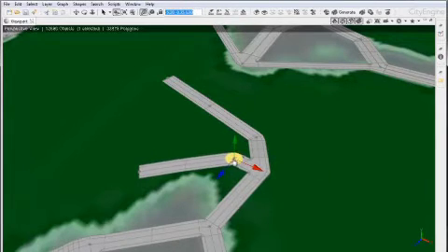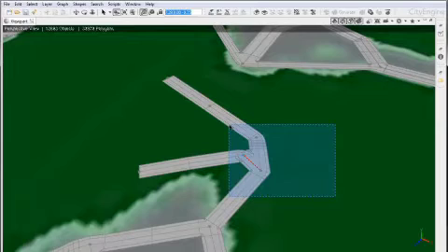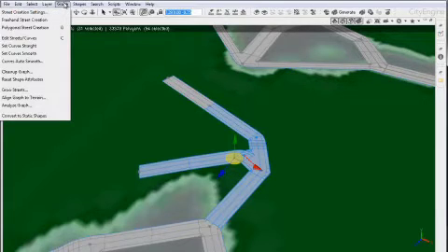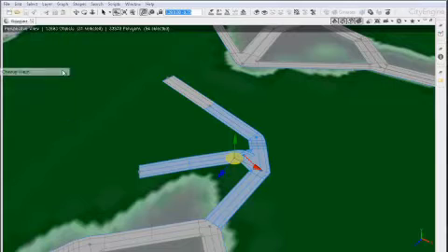But depending on the amount of segments you have in your scene, or the amount of time you want to spend cleaning those data sets, it may also be useful just to use the cleanup tool. So let's select this group of street segments and fire up the cleanup tool. This here is the button. You can also start it from the graph menu. So let's go into the cleanup graph tool.